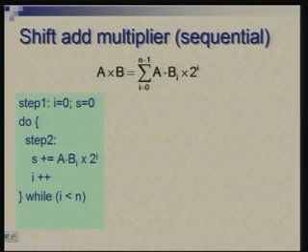So, step 2 is both these assignments. So, actually what I imply is that both these are done together in the same clock cycle. So, for n bit multiplication, this loop will be done in n clock cycles, although I have written it as 2 separate assignments, my intention is to do these 2 in hardware in a single cycle.